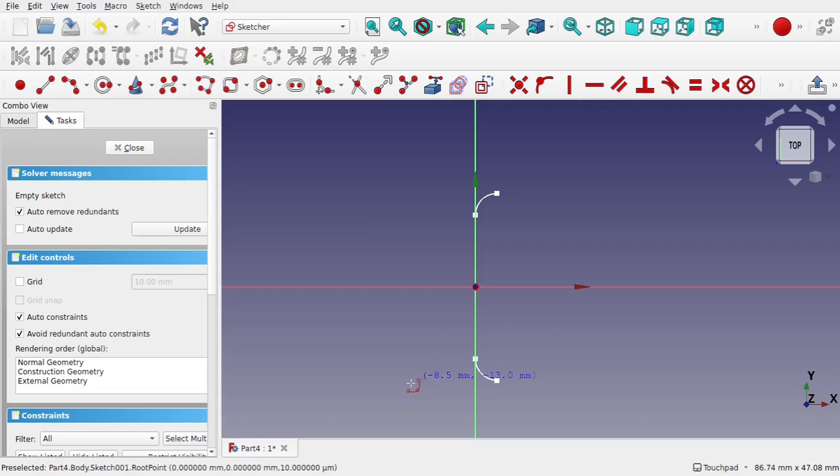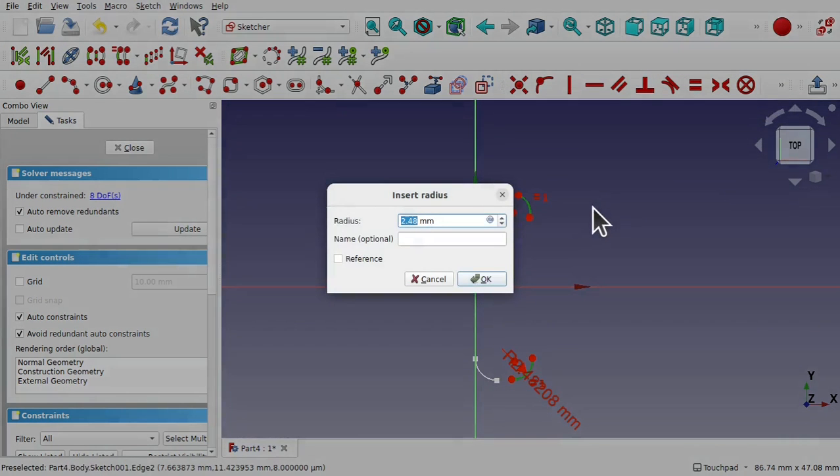Endpoint and rim point arc, and we're going to create the reverse of this. So we want them coming around this way and connecting up like so. But remember that this needs to be on this line here. So we're just going to use this line for visual reference. Let's make the radius of those 3mm.